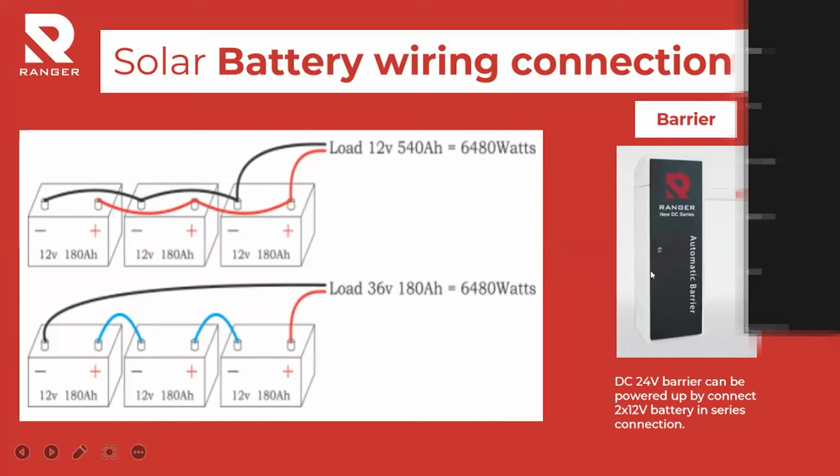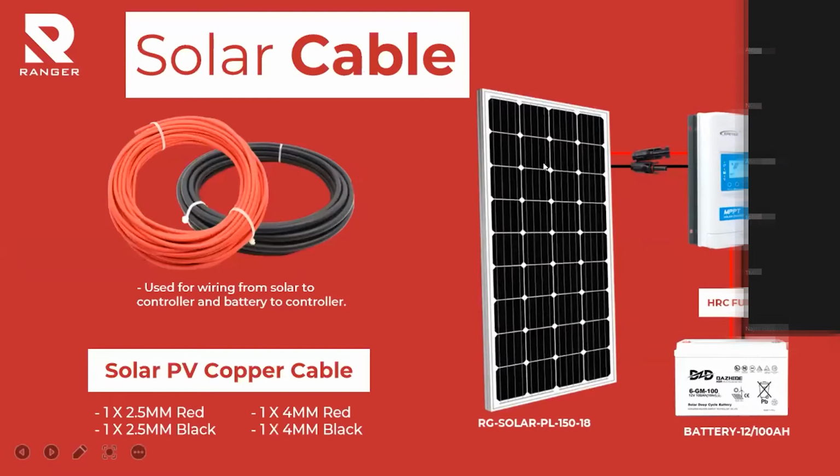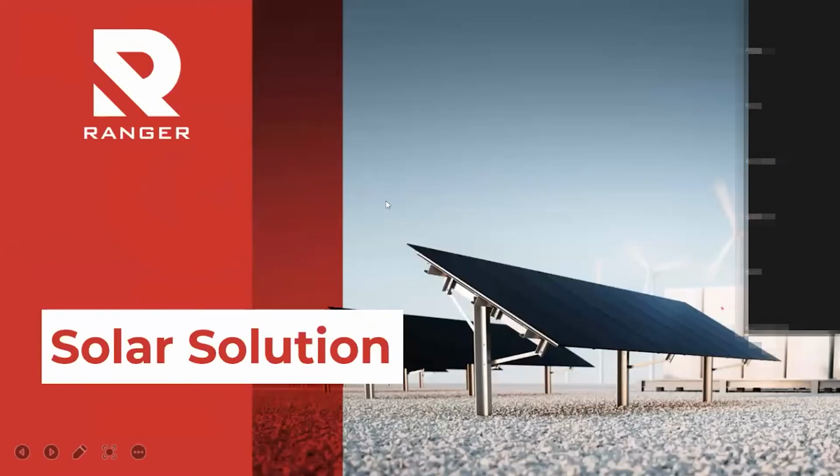I show this example because the DC barrier uses 24 volt. If you want to use a DC barrier with a solar system, you must connect the batteries in series, so that you have two batteries, 12 plus 12, which is 24 volt, that can power up this barrier. Okay, so I will proceed to the solar solution.